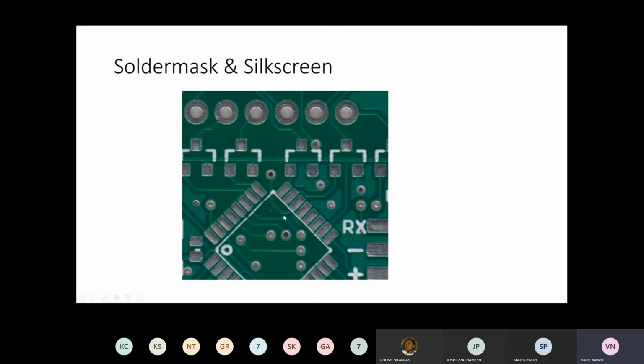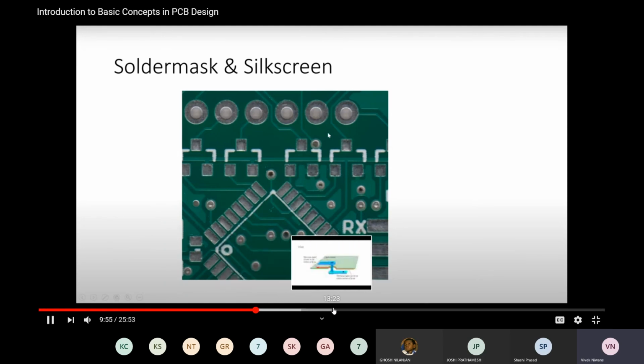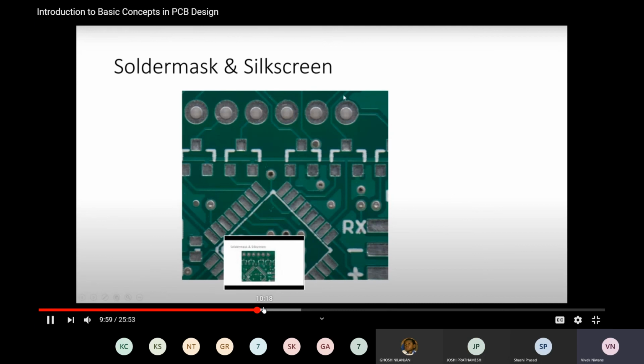If I look carefully at this board, what I can see is I have these lighter green areas, I guess, and then these darker green areas. Where I have these lighter areas, that's basically where there's copper sitting on top of that FR4 substrate. So here I can see I've got a big copper area, right? This is what is sometimes called a copper pour, where copper is effectively in a large plane. All right, so we'll use that terminology, a copper pour. These other skinnier areas right here, these are copper traces. So essentially what's been done is the silk screen has been sat on top of the top layer. And so wherever it crosses over copper, you get this lighter color. These darker areas, basically, that's just open board.